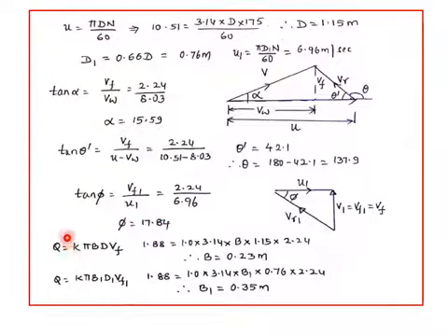We also have what is known as the discharge formula. As we have used in the centrifugal pump, the same formulas can be used. Here K pi B into D is nothing but the area. Since it is a radial velocity flow, Vf is in the radial direction, so Vf is taken as the velocity. Area into velocity gives the discharge. K is the factor which accounts for the thickness of the vanes. If 6% of the area is blocked by the vanes, then we write K as 0.94. If 8% is blocked, then we write K as 0.92.